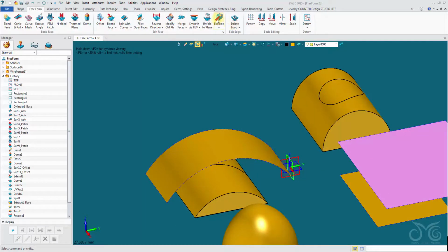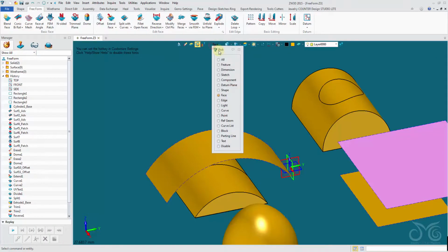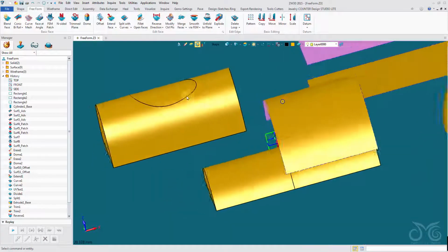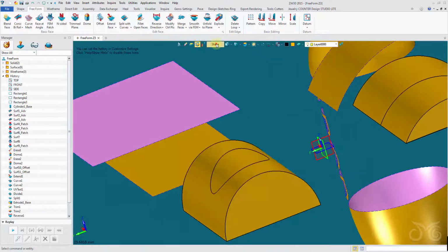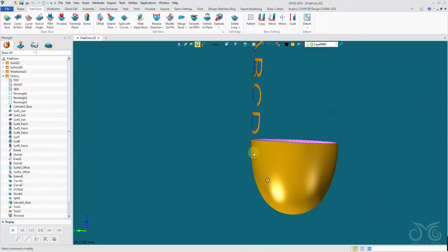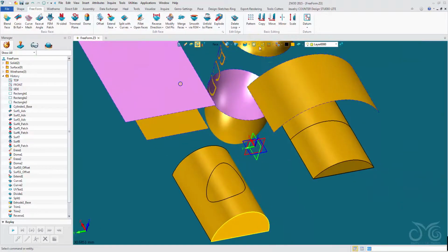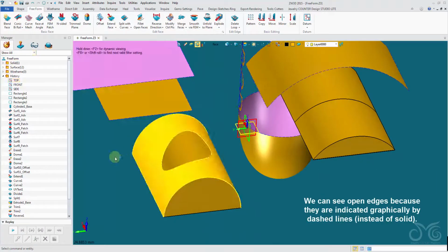Next up we have our explode command. Okay, the explode will separate faces from their base shape. Okay, so let's say we have a shape, this one here, contains 4 faces, or 5 I should say, with this one here. It's a complete shape, but if we use our explode command on one of these faces, confirm, okay, it's going to separate that face from the base shape.